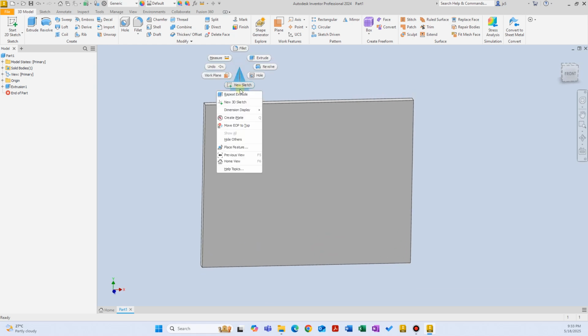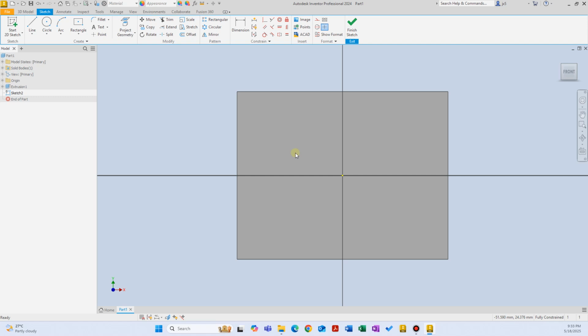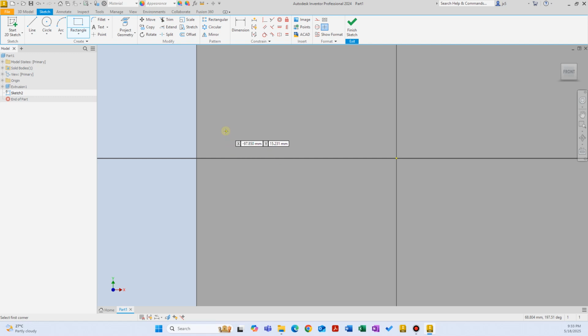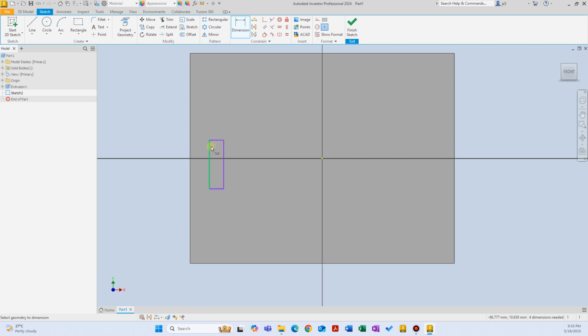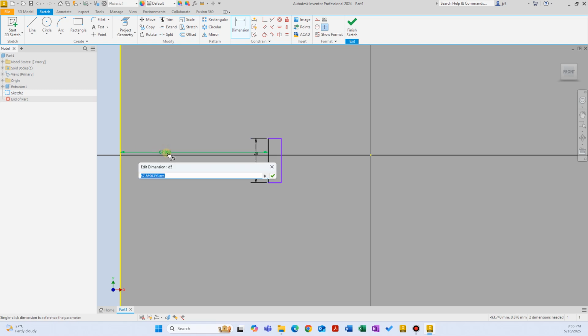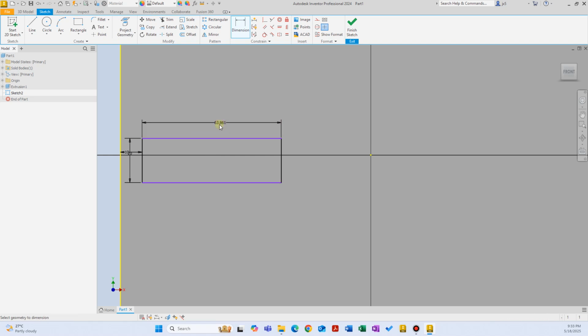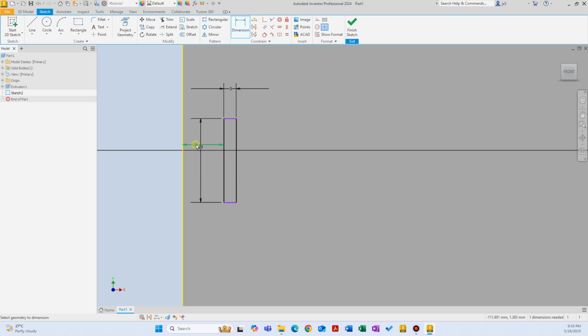So let's continue. Let's create a new sketch on this face now, and let's start with the toothbrush holders. Let's design a quick rectangle here, and let's dimension it and fully define it. So let's say this length here is 20 millimeters, and the distance from the edge, let's give it maybe 10 millimeters, and let's call the thickness 3 millimeters. So we use this 10 millimeter for the distance, and let's keep it that way for the other features as well, so the part stays consistent. And this 3 millimeter thickness should be okay for a 3D plastic part, to make it durable.